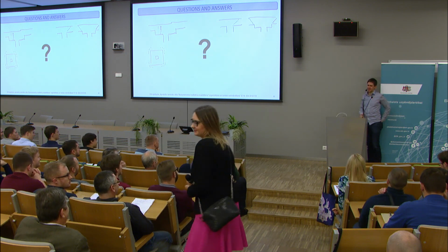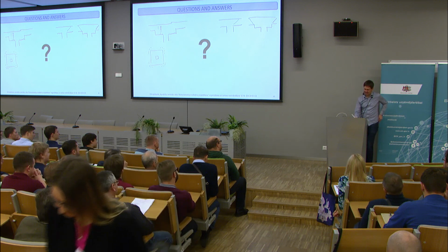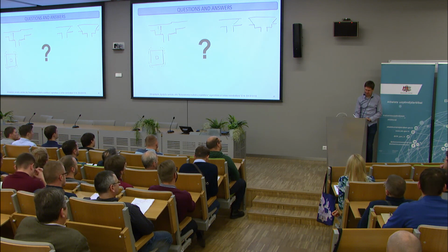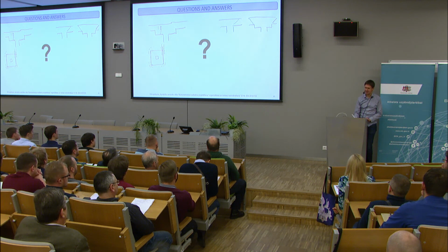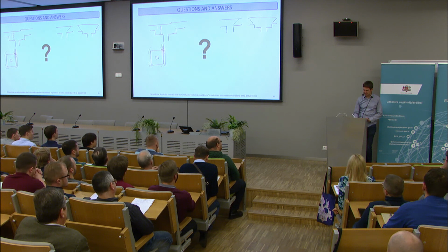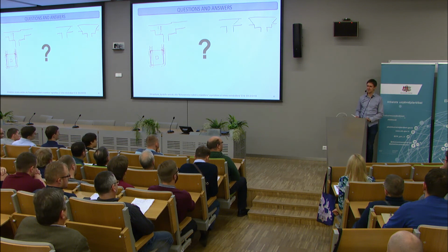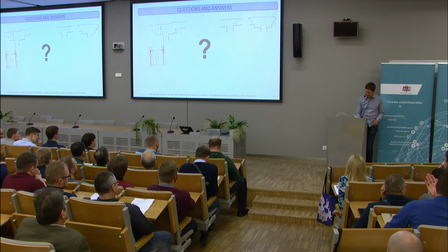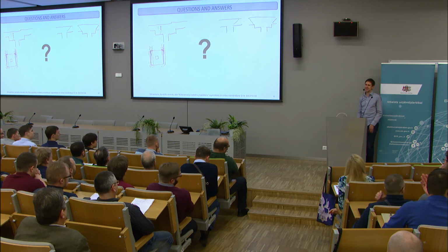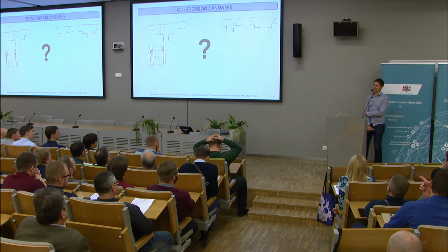I don't think so. Well, if we model it like this, if we put a rigid support in here, then we get a lot of bending moment in these corners. But if we don't put that much flexural reinforcement in here, then we might start crushing the concrete in the corner in here. If there is not that much reinforcement, then we actually redistribute the shear force in there. The effective support will actually get wider. So yeah, this would probably help.